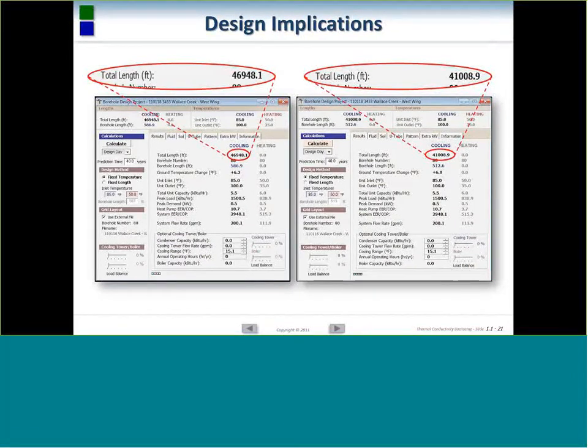Why don't we just estimate, look at some local geologic data and try to figure out what it would be? Well, running a test can get you accurate data on the site and really allow you not only to design the best system based on the best science, but also to potentially lower your borehole lengths accurately, where you'd have a real solid justification to run it.